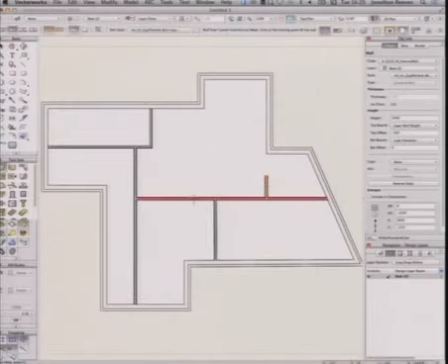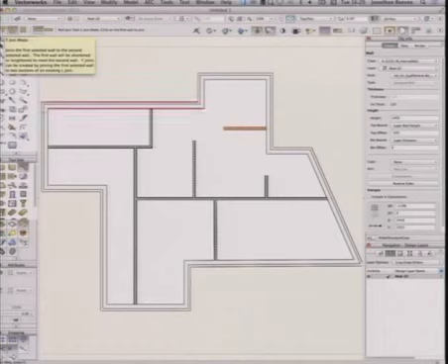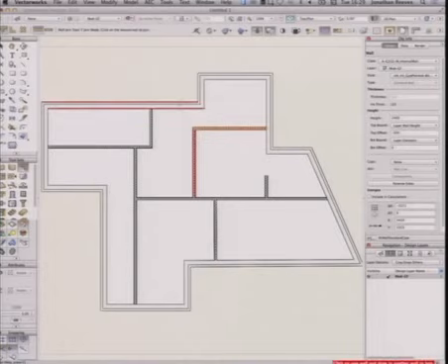Okay, so after you've done some internal walls, the next tool to master after the wall tool on your BIM journey through BIM is the joining tool, and it's the tool here. Have a look at the junctions, decide what kind of junction it is. Is it an L junction or is it a T junction? Very straightforward tool. My advice to you on all of these BIM tools is a little mantra that I've developed. I always teach my people who come to see me. Tool, mode, maneuver. Just keep repeating that. Tool, mode, maneuver. So what does that mean?